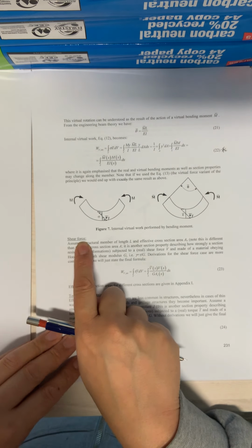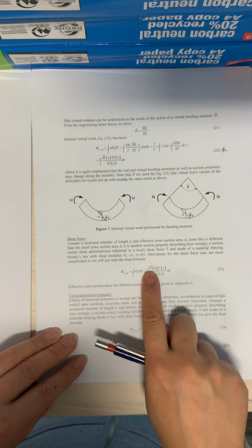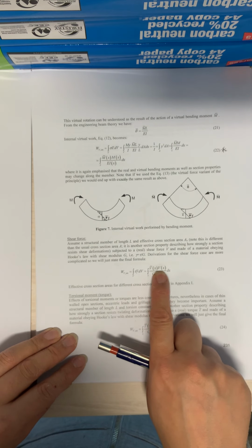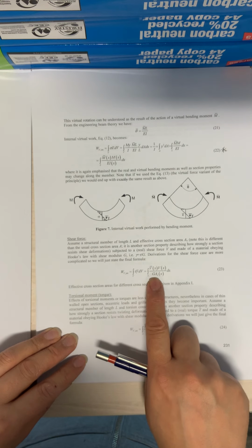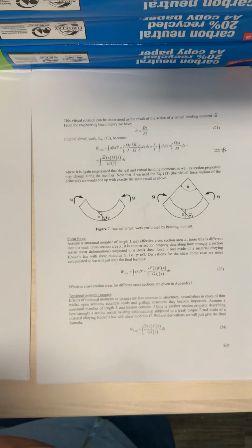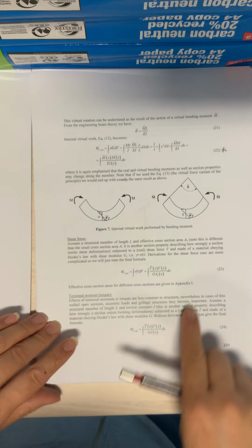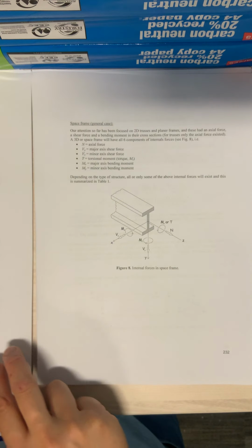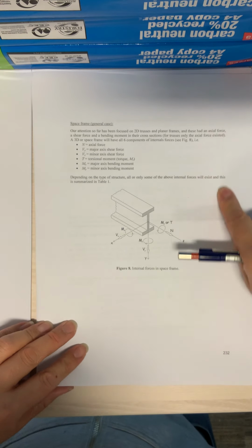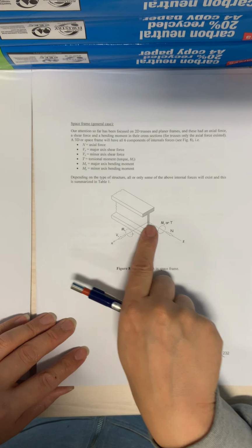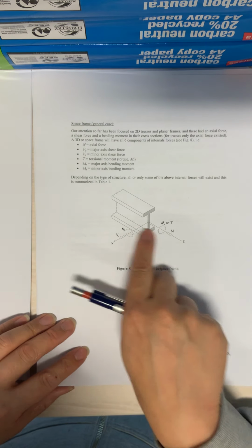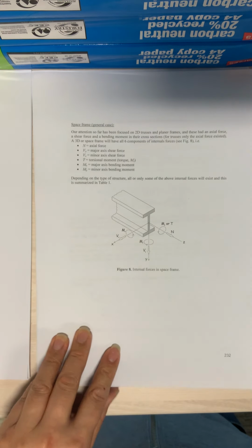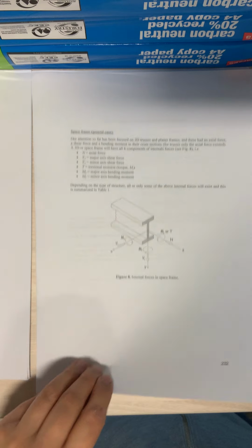So for the shear force, we would get a very similar equation: the real force multiplied by the displacements divided by GA, and that would be your virtual internal work. And then you can apply the same to a torque. And if you wanted to work in 3D, then you've got bending about 2 different axes. So you can consider all of these in your equation.